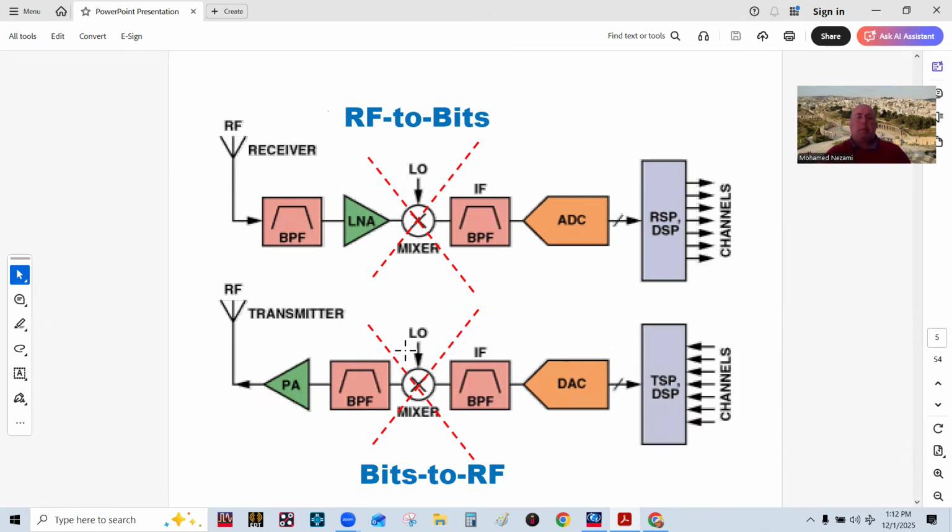Okay, so last time, as you know, we introduced a concept, which is basically to take an RF modulated signal, pick it up via an antenna, filter the interferences out, and bring the level up using low noise amplifiers. And then conventionally, we used to down convert this carrier frequency down to some intermediate frequency, IF, to be able to digitize it.